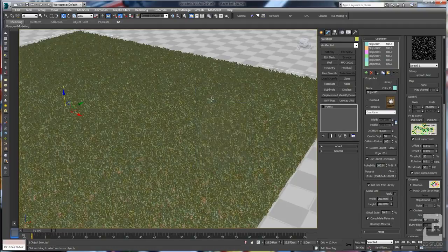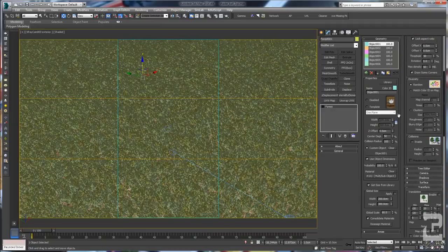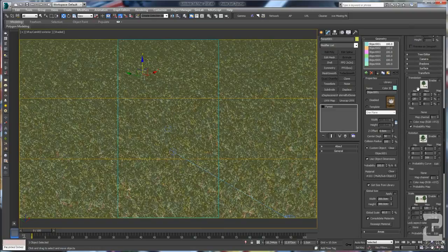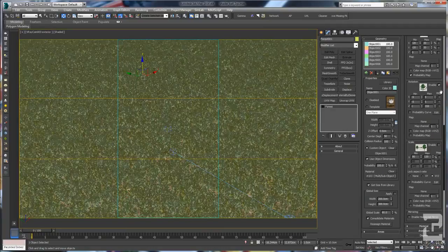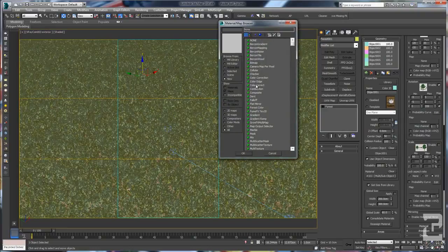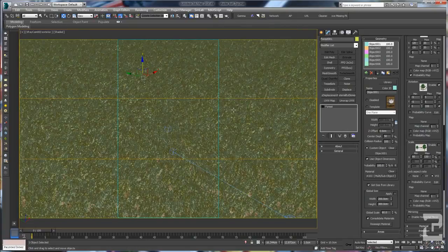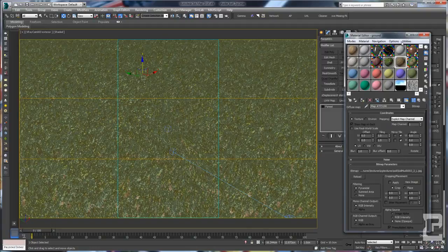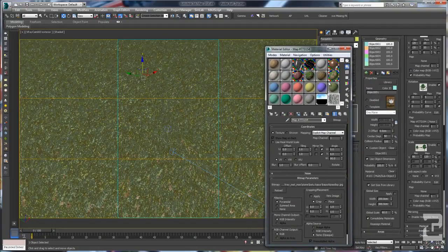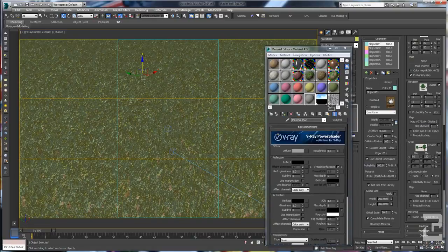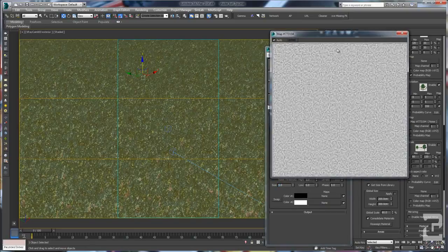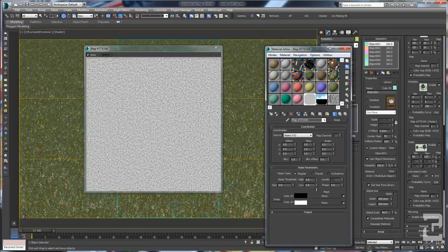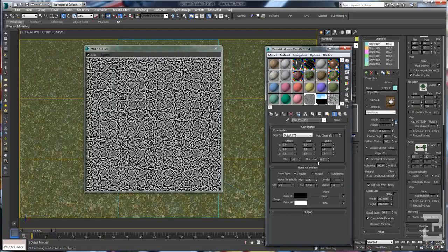And I will go to the camera setting like this, and I'm not going to use any collision for now, and I will play with the transform. I'm not going to use the translation, so I will use a rotation, and I will use map on the Z axis, and I will use noise as in our previous test, on the size 5. Okay, and we can play with the high and the low parameters, so we can have a more distinct black and white map.